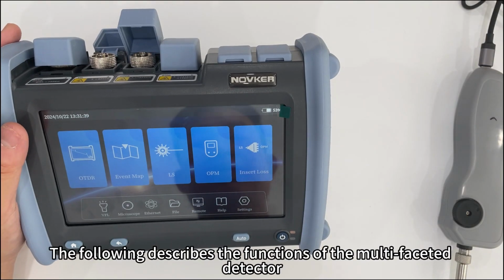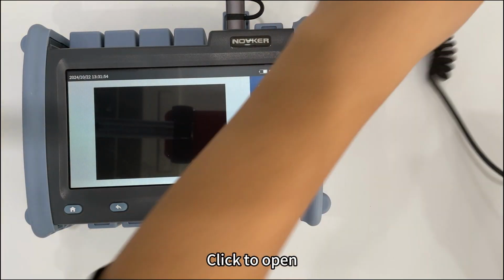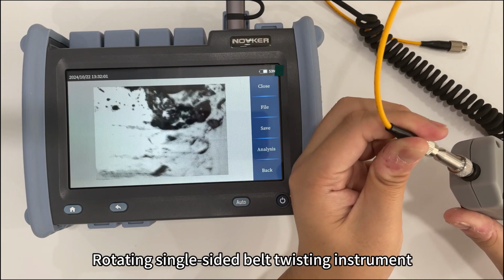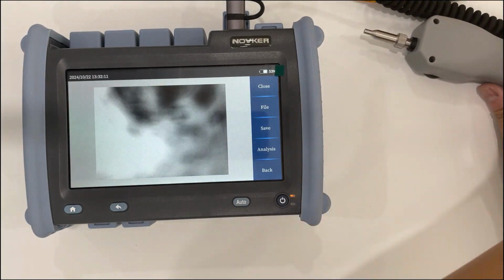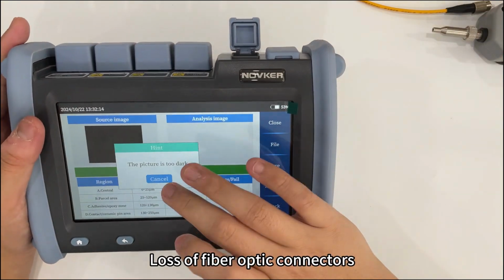The following describes the functions of the fiber microscope detector. Plug it into our USB port. Click to open and connect to our fiber connector. Rotate the single-sided fiber connector and the lossless condition of the optical fiber can be observed. Save can save the current image. Analyze can analyze the current fiber optic connector loss.